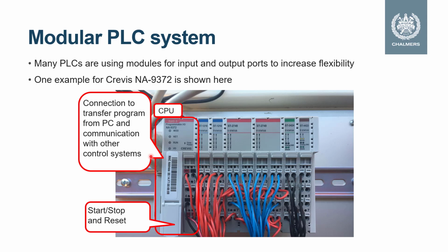Now to the modules. The first modules I have here are input modules, digital input modules, which means that in all these cables I can have digital signals into the PLC system. We can see that we have 0 to 7, 8 signals per module, and I have 2 modules here. Remember, it's only an example. I can put in more or less modules if I want.